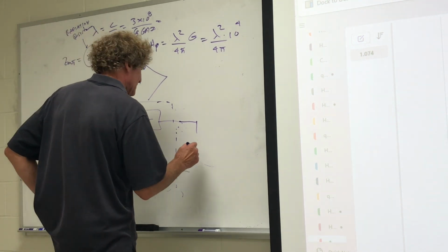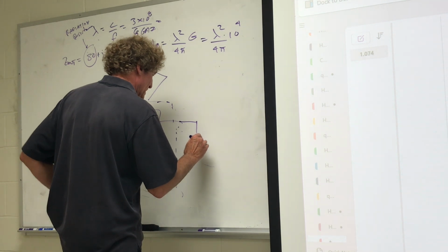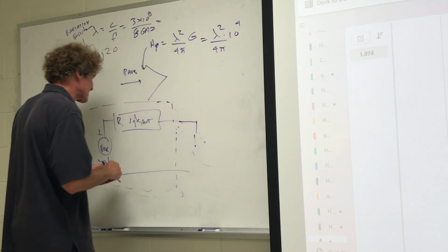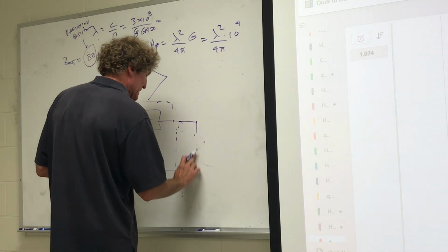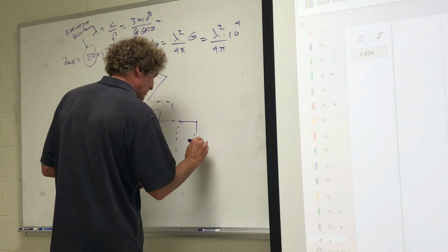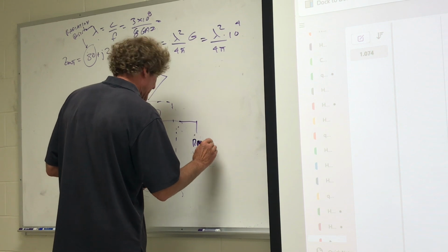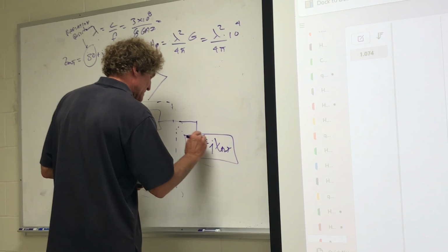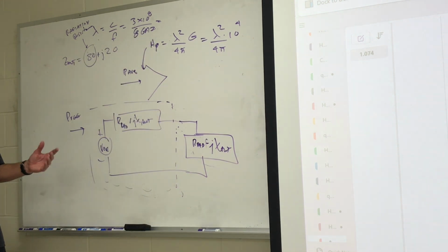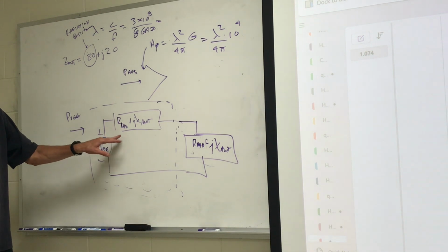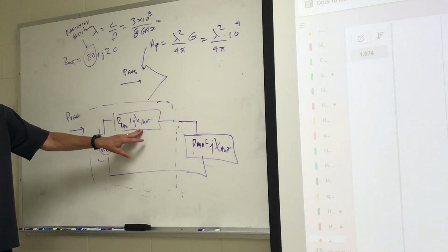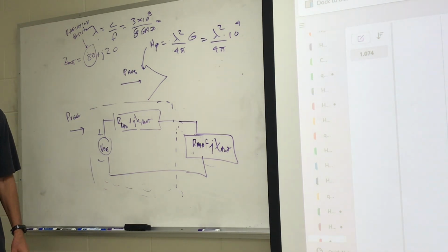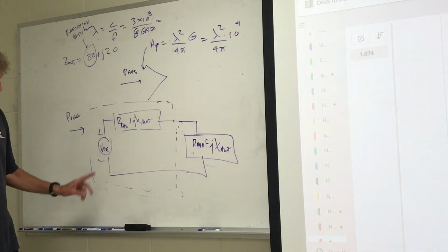So when this is equal to R antenna, I'll call it R rad. Actually, the book does call it R rad, and I've been calling it R rad, so just call it R rad. And this is going to be R rad. And this is going to be minus JX antenna. Now this is just to find V open circuit. This is to get maximum power. If the antenna has impedance, real plus J imaginary, JX, the conjugate would be R minus that, right? J, it's called the conjugate. We're not putting a load on, we're finding VOC, right?